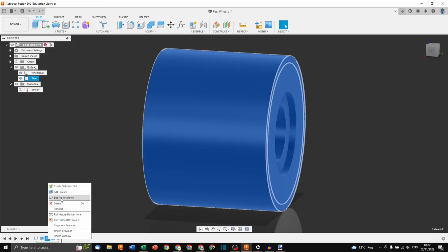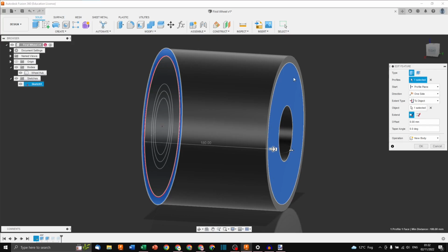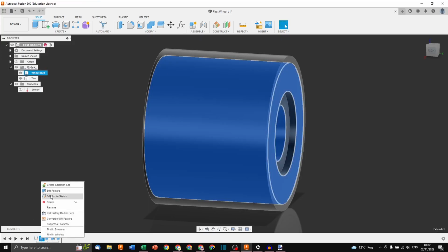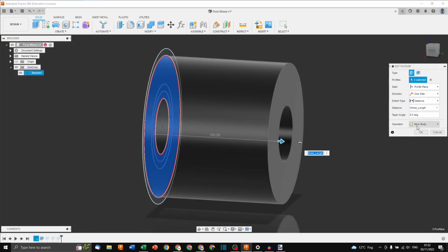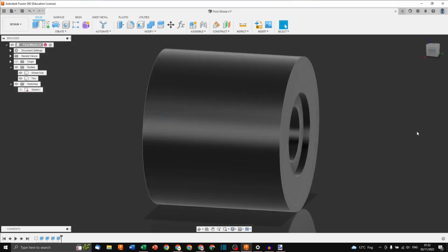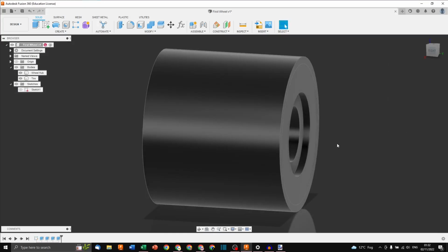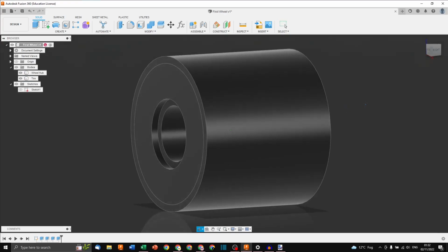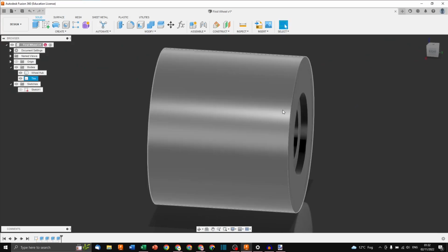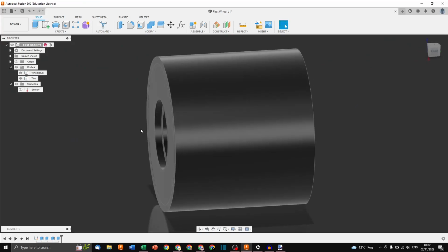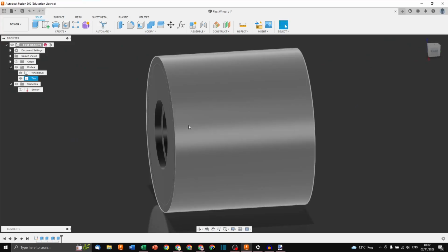But if I choose extend to object, it's always going to go to this object. So I don't care whether I put 180 or wheel length or 200. You see, the wheel automatically gets bigger. So not only does the tire get bigger, also the bearing seats are still at the right place. That's because we only have one sketch and it's all parameterized.